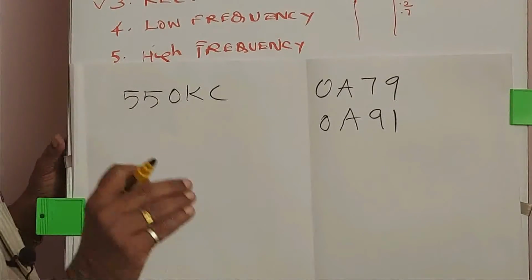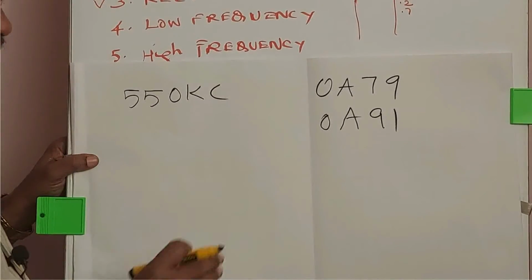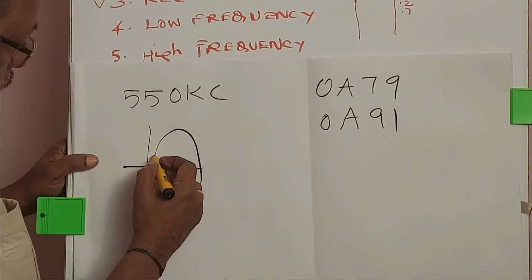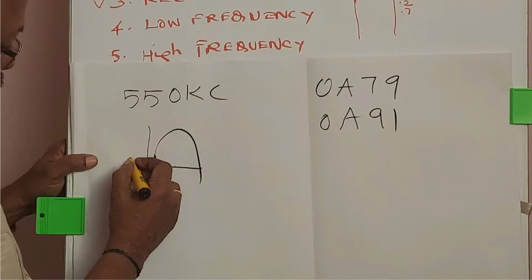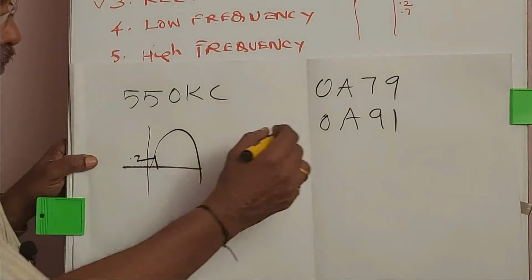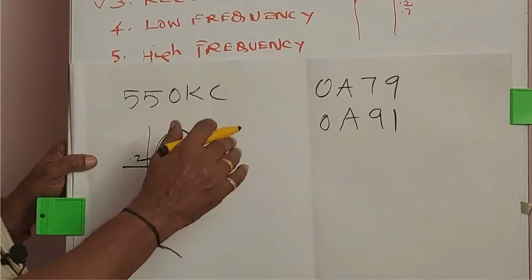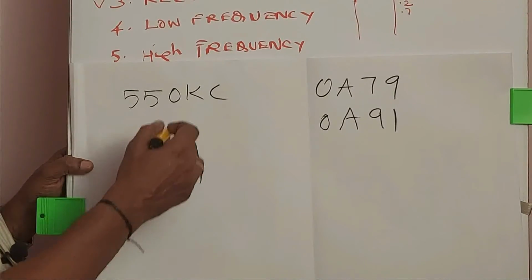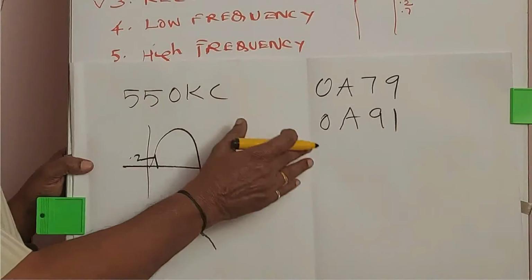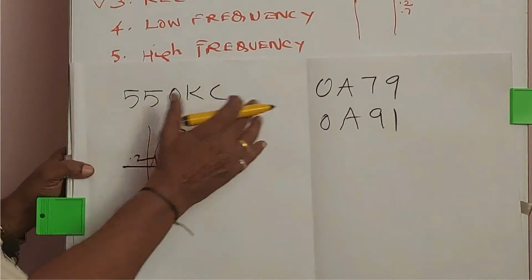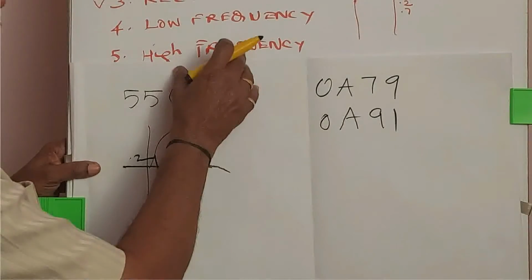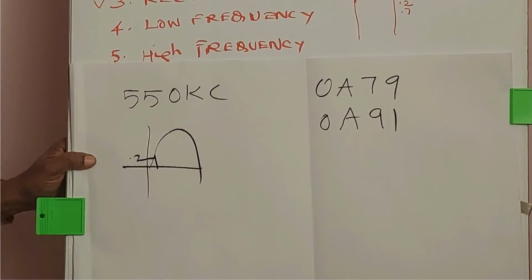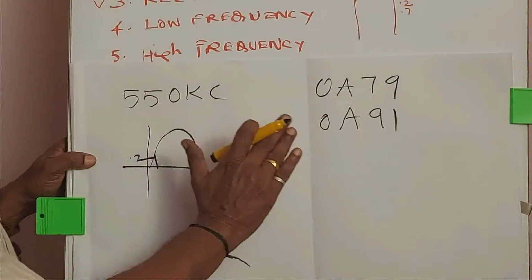Normally, for example, in AM demodulator circuits, they are made of germanium because they have to rectify starting from 0.2 volts. If you use a silicon diode, it will rectify only from 0.7. There may be certain information between 0.2 and 0.7. Therefore, only germanium has to be used. Like that, these diodes are useful for high frequency rectification only, in communication equipment.